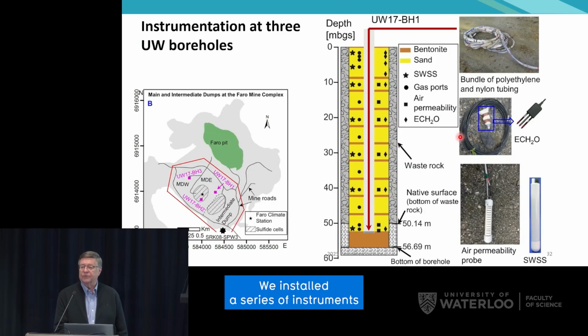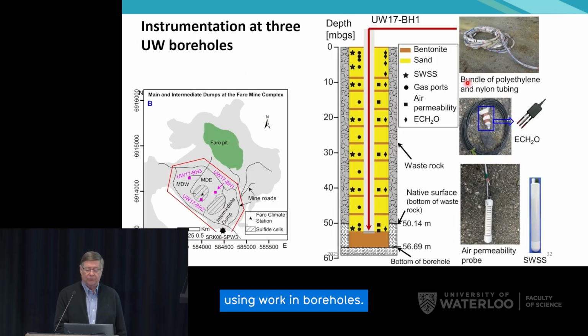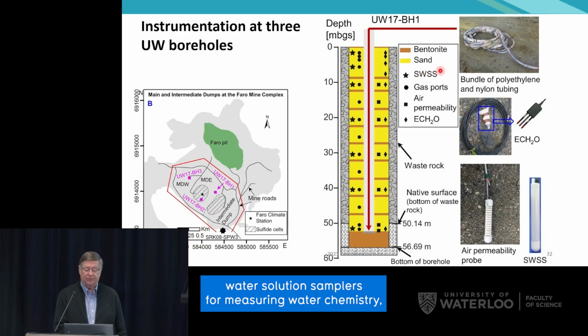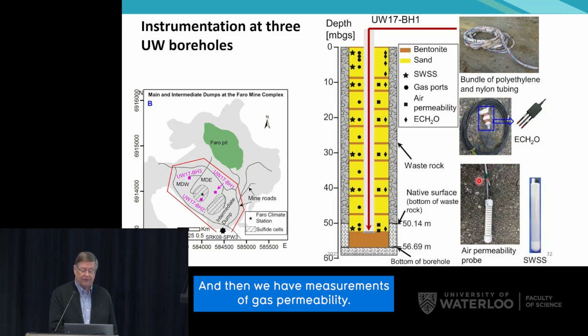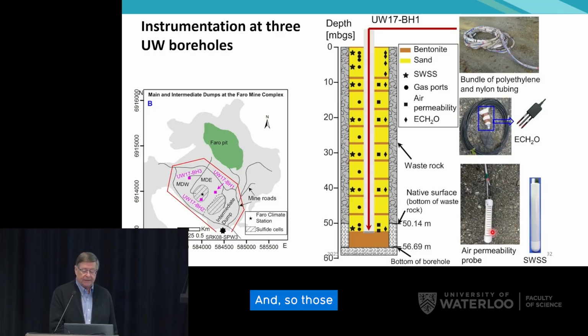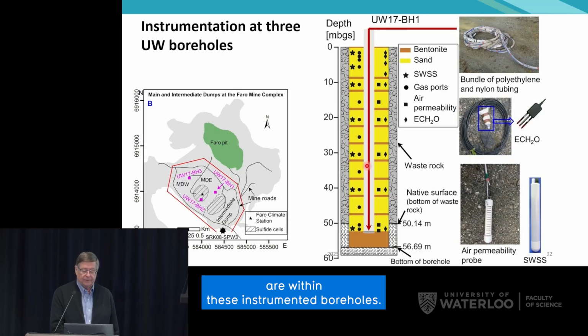We installed a series of instruments using boreholes. So we have soil water solution samplers for measuring water chemistry, gas sampling ports for looking at gas concentrations of oxygen, CO2, nitrogen, and argon. We have measurements of gas permeability, temperature, electrical conductivity, and moisture content probes. And so those are within these instrumented boreholes.